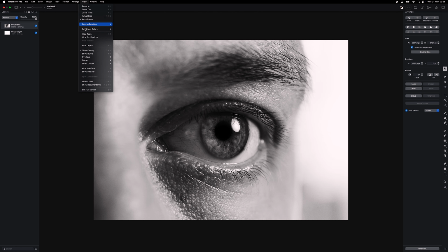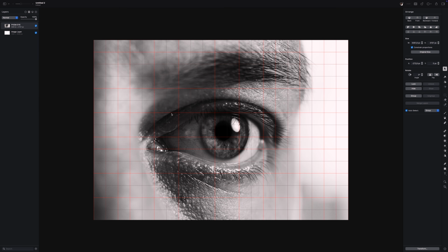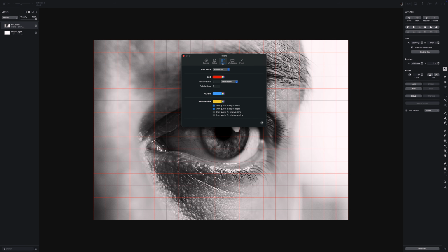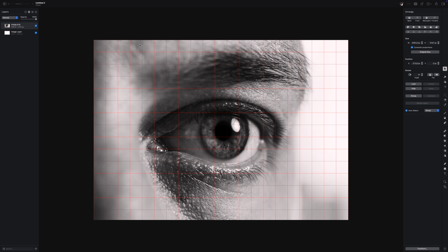We're going to say View, Layers, and then click on Grid. This is going to overlay a grid across our entire reference image. We want to make sure our grid dimensions are fine. We're going to work with a 2 by 2 centimeter grid. So make sure that in settings, over there by ruler, you set the grid line at every 2 centimeters. Mine is already set at 2, so this should be fine. Each grid line now is at exactly 2 centimeters, vertically and horizontally. Okay, those are our guidelines for the grid.